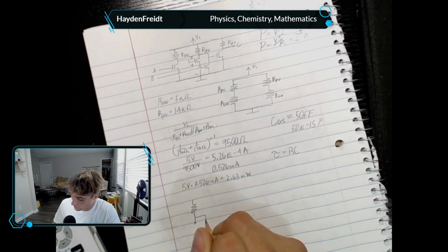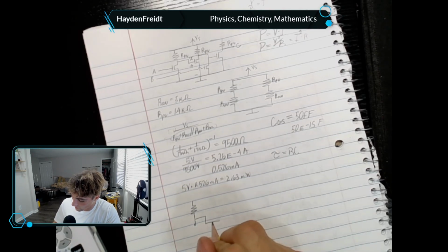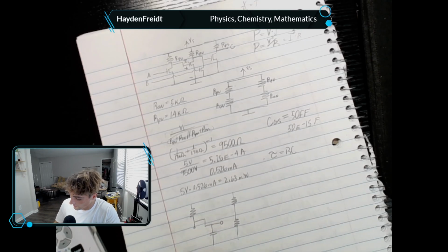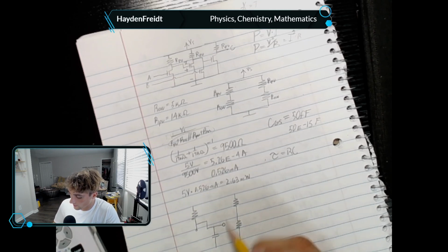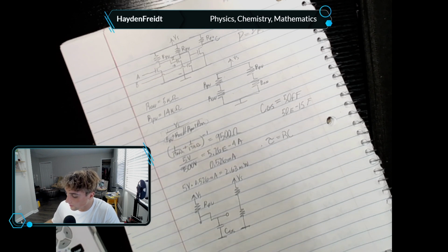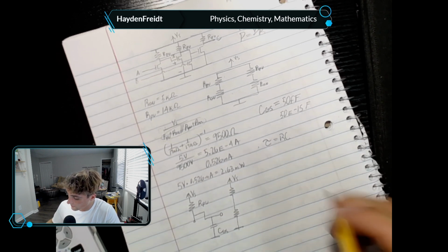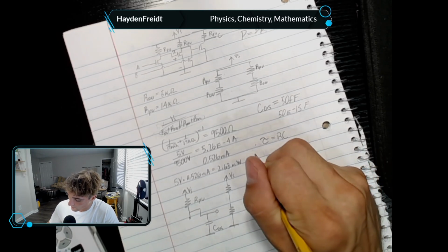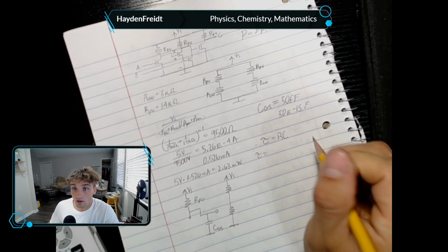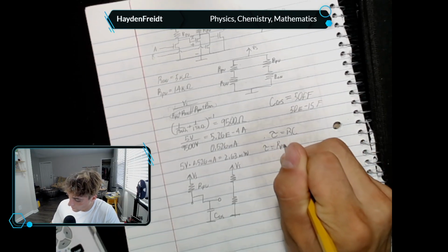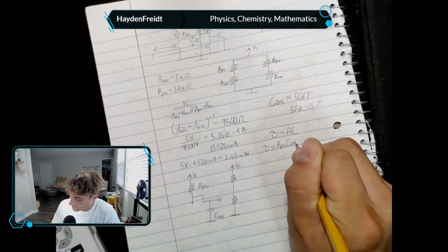We're not connected to the other transistor's input here, we have an open circuit. That's how we would model it to define the rising edge time constant, so tau equals RPU multiplied by C gate source.